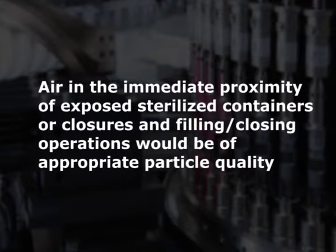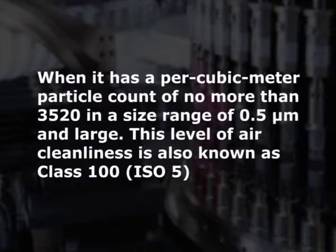be of appropriate particle quality when it has, per cubic meter, a particle count of not more than 3520 in a size range of 0.5 micron or larger. This level of air cleanliness is also known as the class 100, ISO 5.